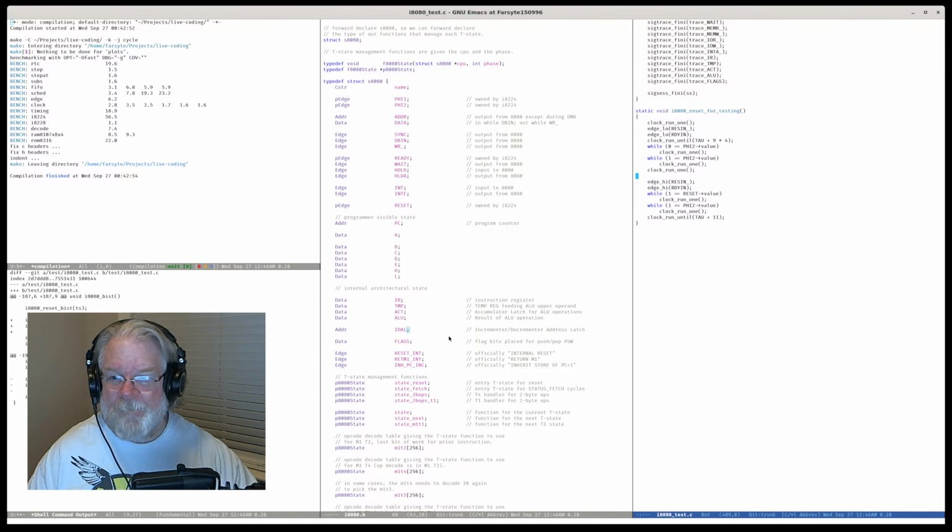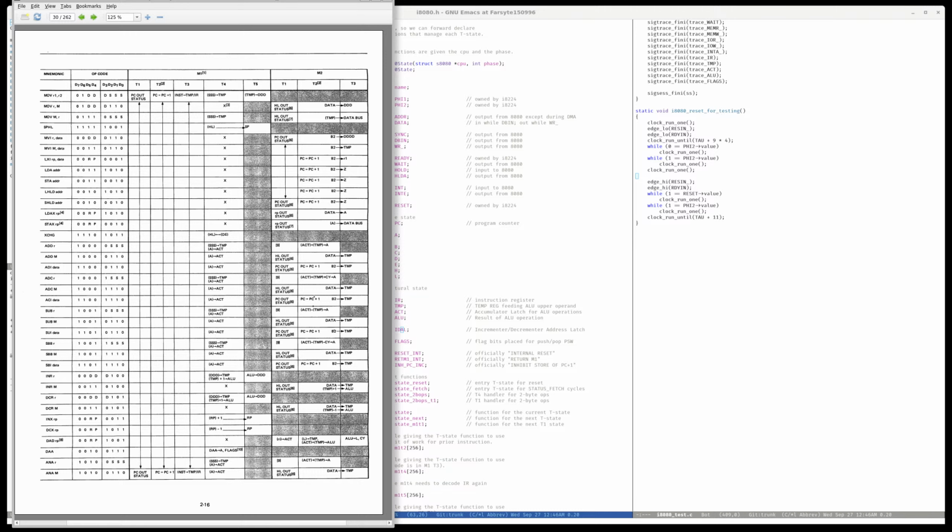And back to our coding, and now we have the incrementer decrementer address register handy. So if we go back to our PDF, we now have the correct paths to do the increment INX and DCX. Remember, it's increment or decrement, so we use it for increment and decrement. DAA would fit inside this set of things we're doing, but it's not really increment or decrement. Let's see, just increments and decrements, and then if we have time, we will move onward to other single byte instructions.